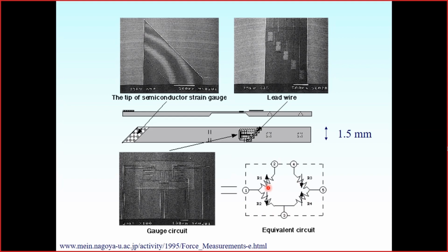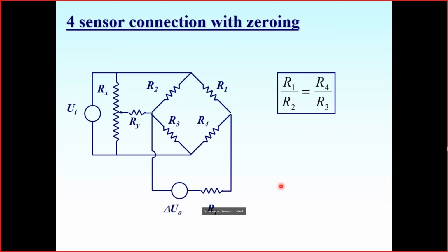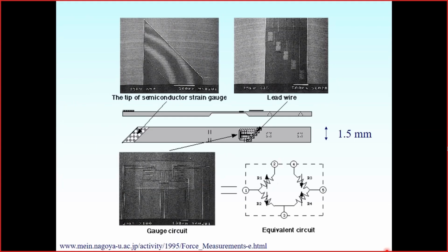To balance such a bridge, when we have no direct access to any of the resistors included in the branches, we may use some kind of special circuit. Here we actually have two outputs from one side, which may be used for connecting balancing resistors that balance the bridge.